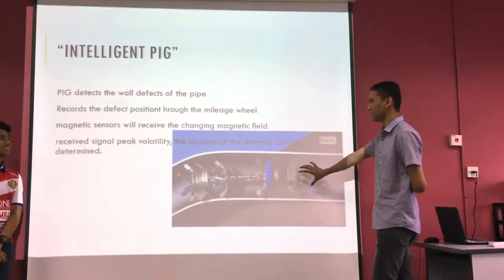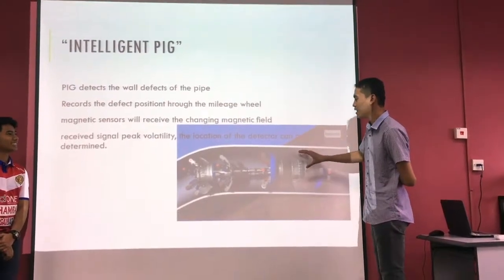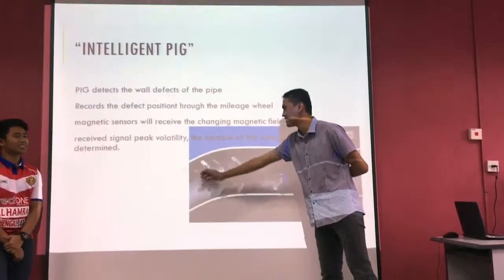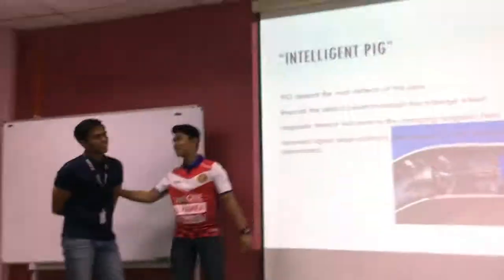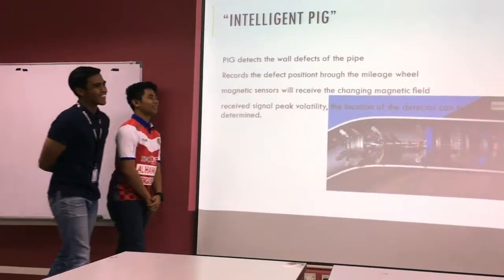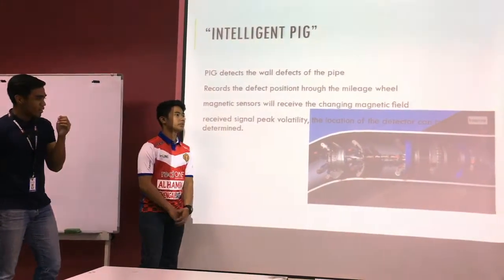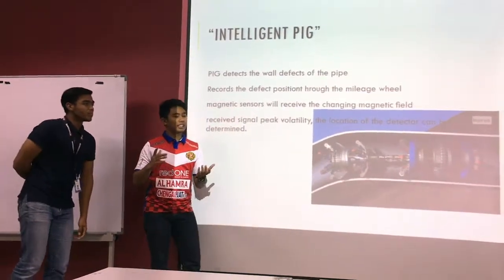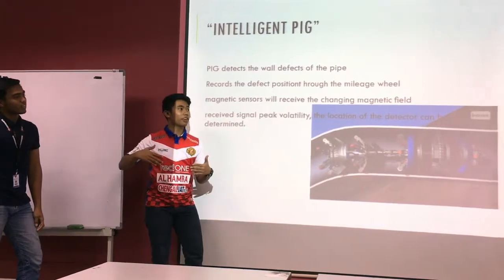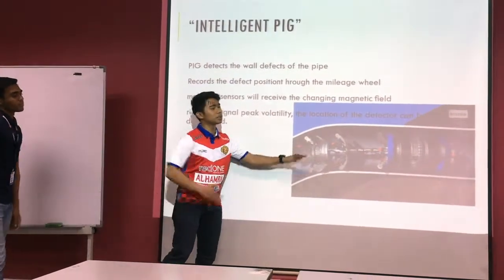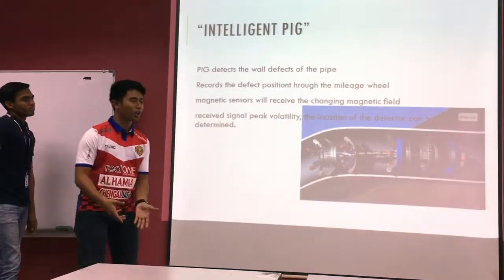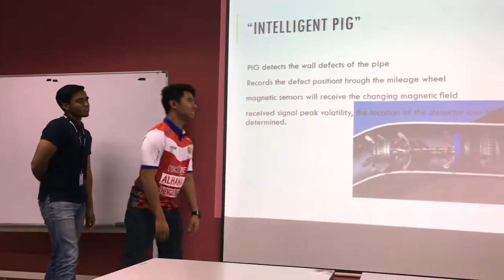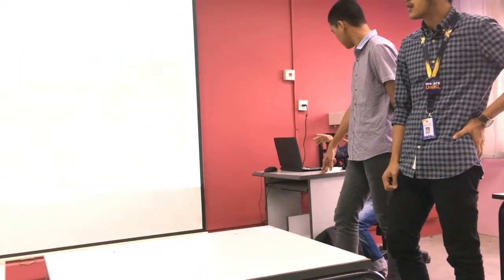Okay, actually these pipes go through inside the curves, right? So how do they go through the curved pipes? Intelligent pig. So we can pass everything. No, the machine. When they put the intelligent pig inside, they also put pressure. The engineers have already calculated the amount of pressure to put for the intelligent pig, so that it can go to the exit hole and they can just take the intelligent pig out. And if the pig gets stuck in the pipeline, they will send another pig, a regular pig, not an intelligent pig, to push it.